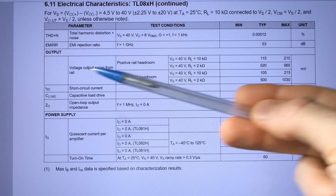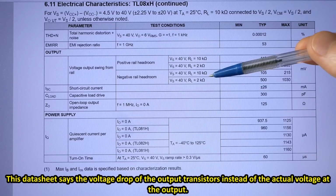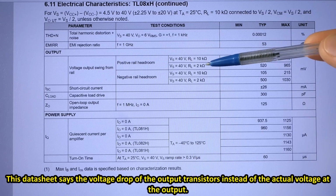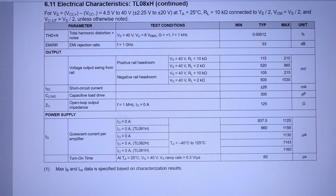And the output voltage swing. In the positive rail, the output transistor basically drops up to 210 millivolts, and in the negative rail, 215 millivolts, when it's loaded using a 10 kilo ohm resistor. Of course it drops more, about 1 volt, when it's loaded using a lower resistance, 2 kilo ohms. This seems like a FET-based one.